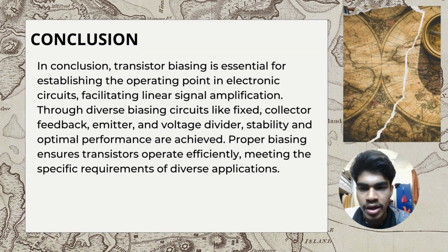In conclusion, transistor biasing is essential for establishing the operating point in electronic circuits, facilitating linear signal amplification. Through diverse biasing circuits like fixed, collector feedback, emitter and voltage divider, stability and optimal performance are achieved. Proper biasing ensures transistors operate efficiently, meeting the specific requirements of diverse applications.